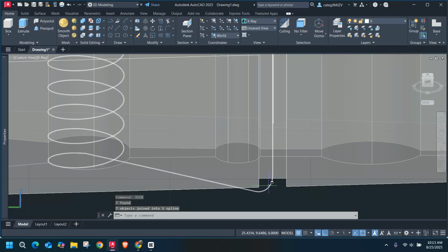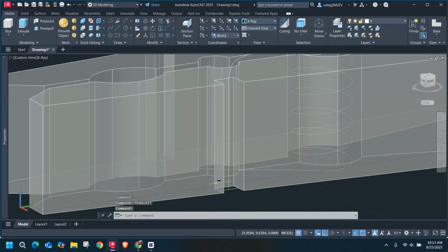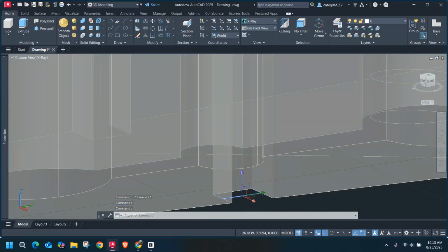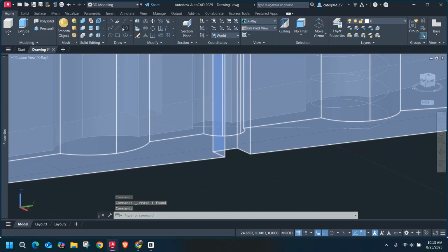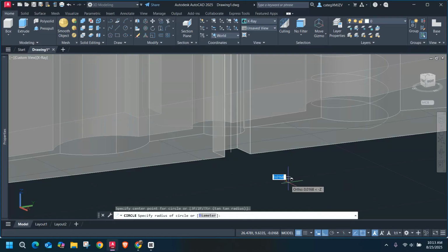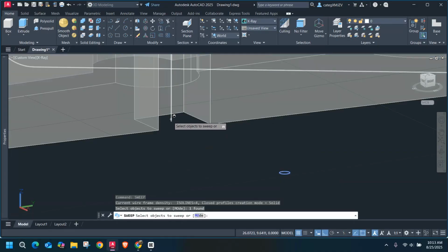Now, hopefully we're happy and it's all one piece. Now, that's all good, it's all fine and dandy, but if it doesn't sweep, we're all out of luck. Now remember with sweep, it doesn't matter where you create the actual object you're sweeping, and remember, we are just doing a circle. So it's not gonna matter the orientation of it either. So go ahead with your sweep, collect your object, and then sweep your line.